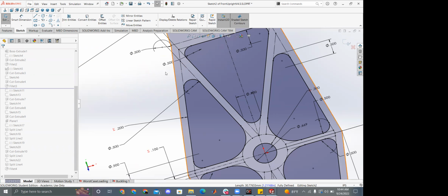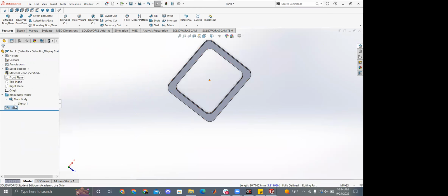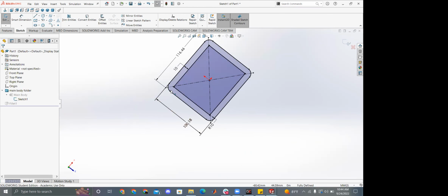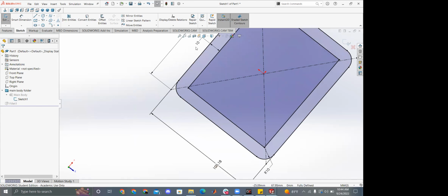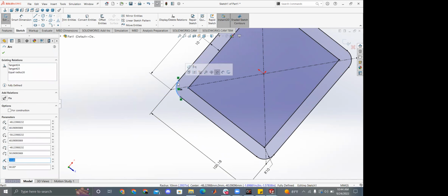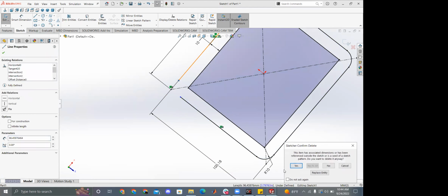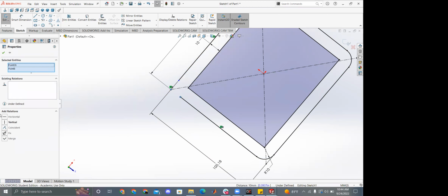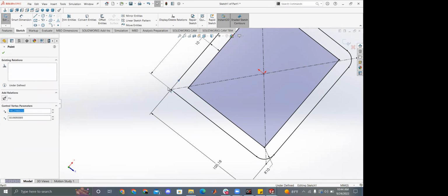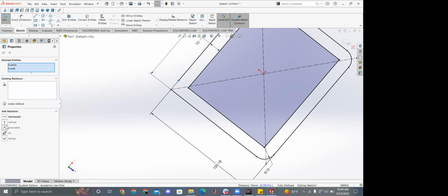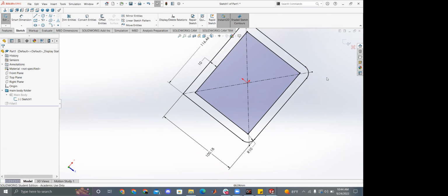Yeah. Once you create a fillet, it's semi-permanent. If we go back to this part, say I wanted to remove this fillet, I don't want it anymore. Well, the only way to do that at this point is to delete this arc, delete this line, delete this line. I guess you can leave it, you can extend it. Oh yeah, that's true. Delete the arc, and then I have to set these coincident again. And I have to do that for every single one. And parts usually have a ton of fillets on them, so that's not a great solution to do.